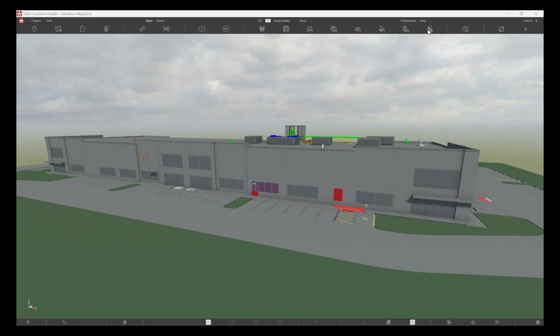Now, while I'm on the topic of automation, I do also want to talk about the Revizto scheduler. That's another app that's downloaded automatically when you get Revizto. Basically, what that does is allow you to automate your uploads into the Revizto software. So let's say you're doing model updates once a week, and every Friday you have a new model file that can be uploaded. You can set up the scheduler so every Friday at 10 p.m. the model will be uploaded from Revit straight into Revizto and keep all of the upload settings that you had previously set. So that's just another great tool.